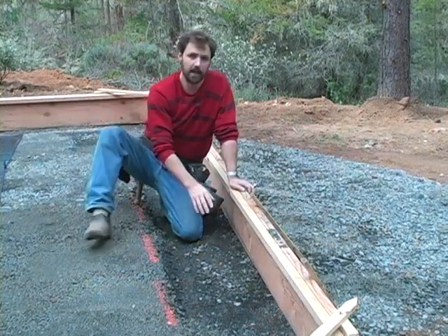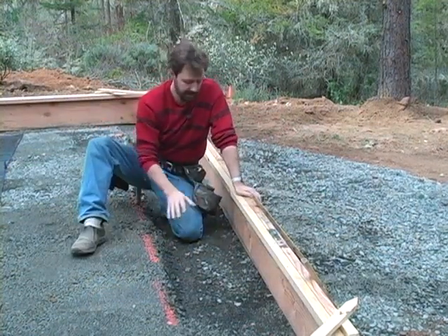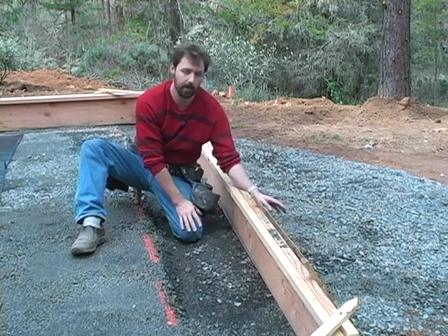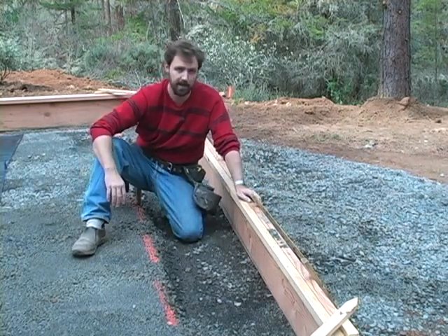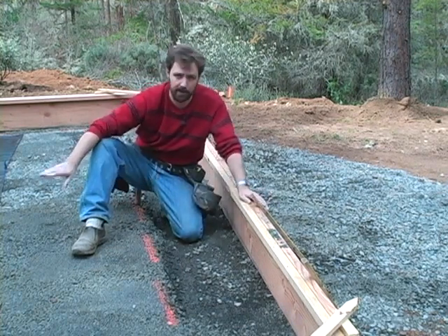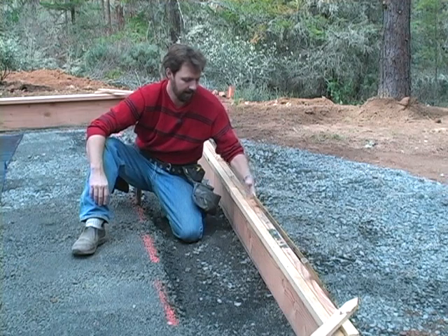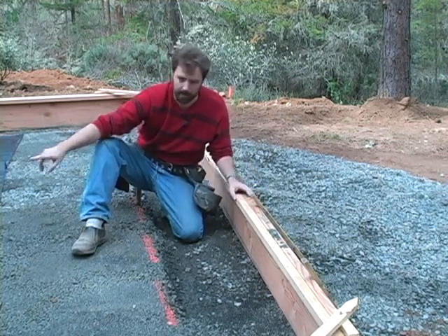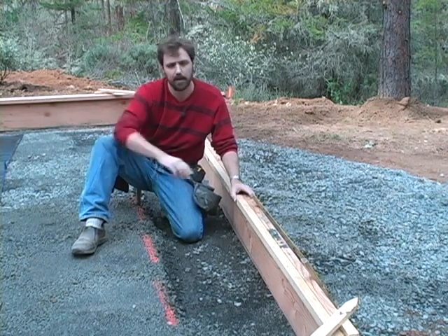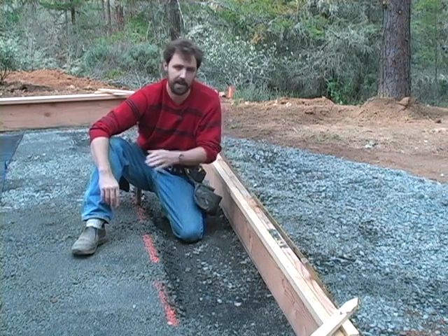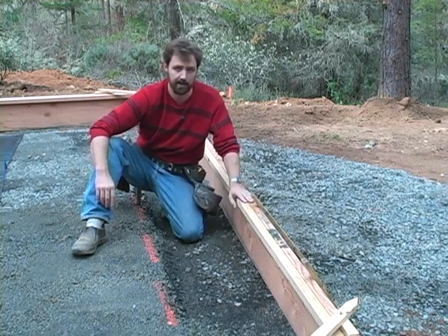Now if you have plumbing or electrical that you're wanting to bring into the building, you'll need to cut some trenches down below grade here. You need to check with your local code to find out what the depth of the trench needs to be for electrical and plumbing lines, and then come back into your building and run to wherever you need to go with those lines. It's important that you straighten your form boards first so that if you're targeting an interior wall to bring your plumbing line up in, for example, you're coming from a square line and measuring in the right direction. If you measure that distance and bring your lines in before you straighten your forms, when you actually build the house, you could be off with where that wall is placed.